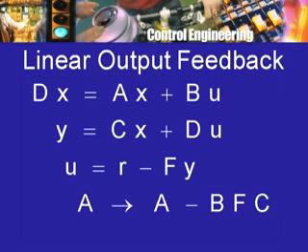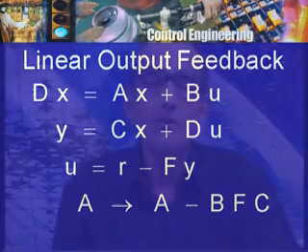which determines the feedback in such a way that the eigenvalues of this new matrix A minus B F C have appropriate values. So, this is going to be a different problem now, and this has been studied quite extensively over the last 30-40 years. Now, this time domain approach, and the time domain approach of course in simpler cases turns out to be the study of linear time invariant differential equations of the state variable form usually.